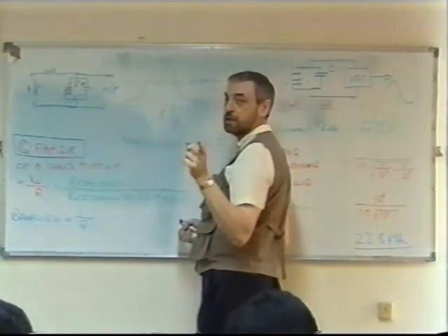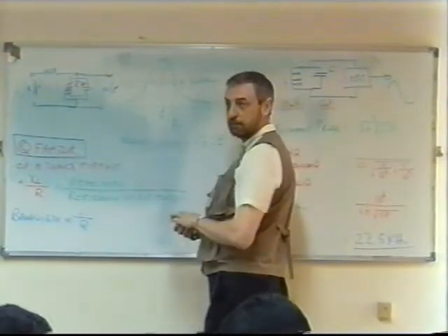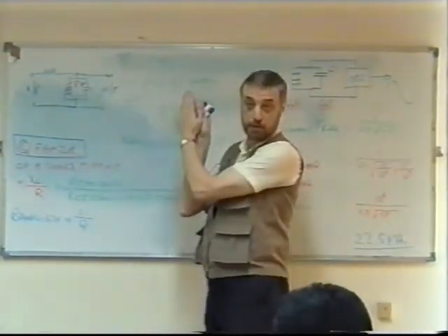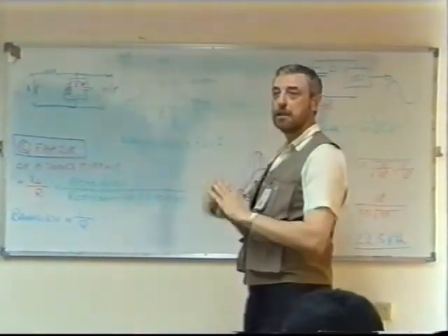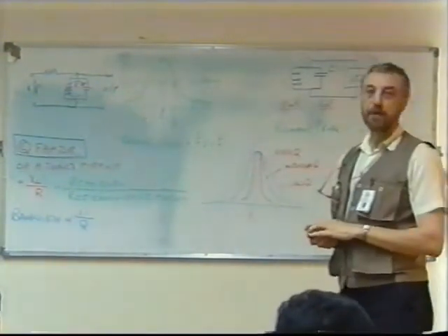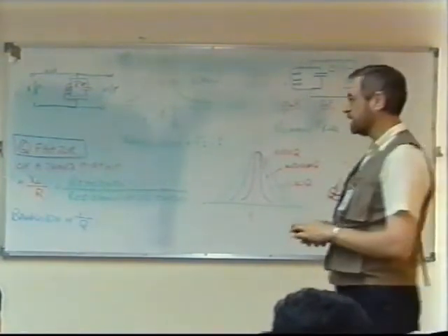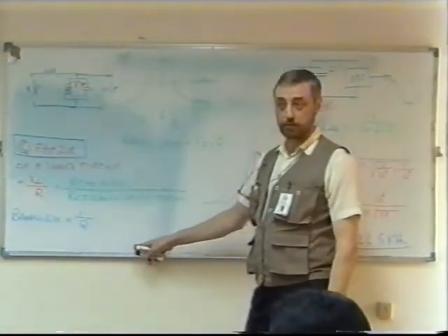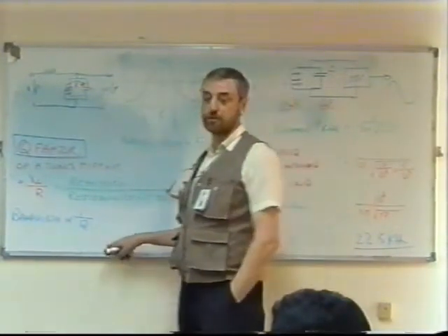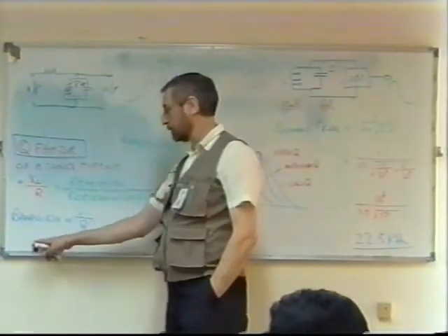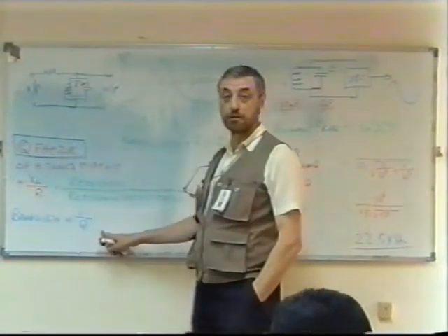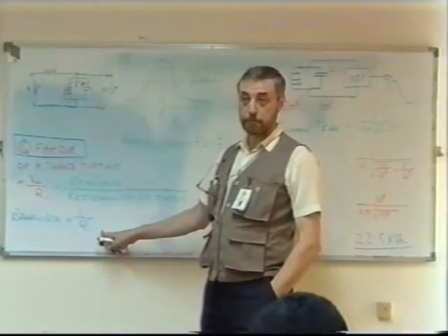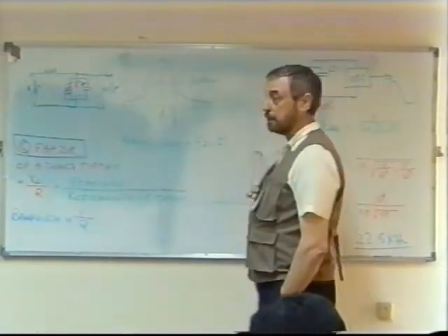For very high Q circuits, that formula would be about right, because these frequencies are very close to the resonant frequency. For lower Q circuits, it's less accurate. I'm not saying it's wrong, it's just that I didn't want to give it here as an absolute, because for a start in this course it wouldn't be necessary. We don't need to know the formula. All we need to remember is it's inversely proportional to Q. That's the reason why I didn't give that formula.